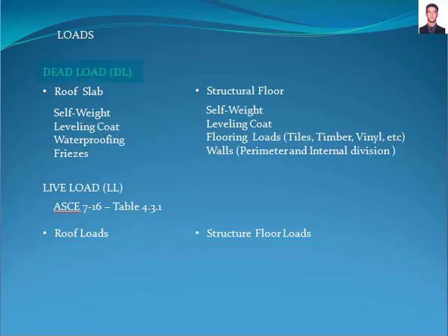Dead load definition. The dead loads are all those loads that belong to the structure, such as the weight of the concrete and the weight of all the construction materials that will be incorporated into the building, such as leveling coat, type of floor, or waterproofing of the roof. To find the specific weight of a construction material, it is recommended to look in the vendor catalog. There are several generic tables and pages that you can use to obtain the information, which have to be approved by the authority before using them.